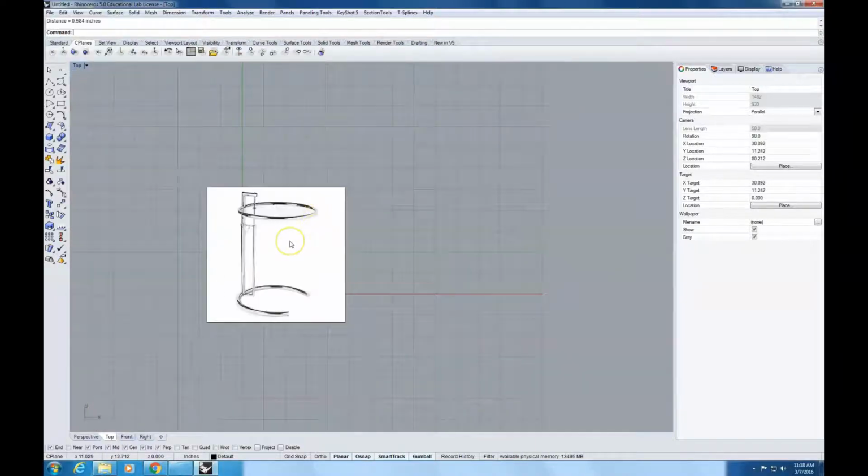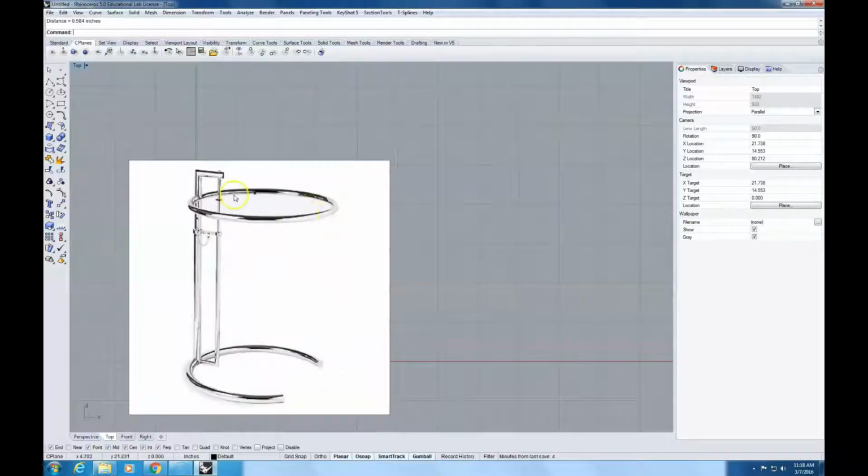So a couple of things. In this case, I'm going to teach you guys a sweep. So if you analyze this donut, it's basically a donut. It's really made of a circle that is half inches in diameter. So before I do that, I'm going to click here and then hit diameter and then type 0.5. So here's ½ inch. And then it's also made of a circle that is 18 inches in diameter. Okay? So I'm going to click here. It should be in diameter, so I'm going to go 18.